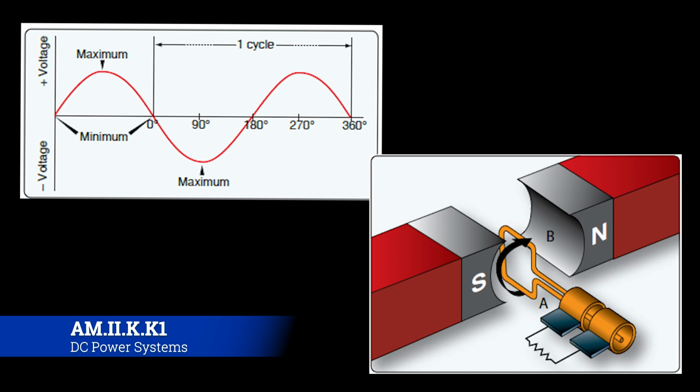Those electrons flow down the armature into the brushes. Now the brushes are being depicted there. Those little black blocks snug up to the commutator right there, and then they're connected with a resistor. It basically means that it goes to a load. In this case, it's going to be everything on the airplane. But that's basically how a generator operates.